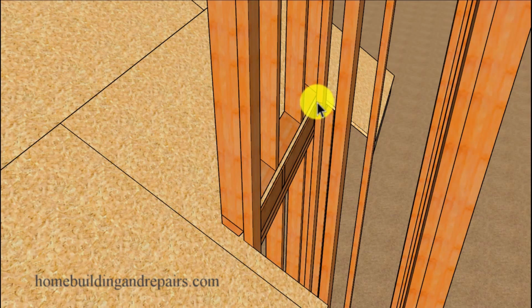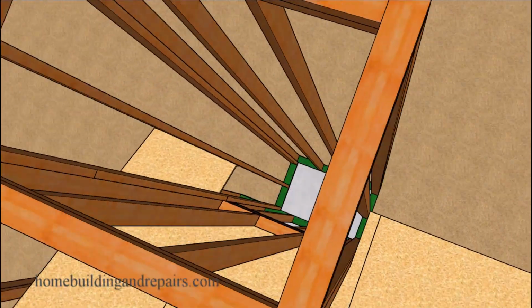Now here's the example of what I was talking about. We're not going to be coming off of this mark here. We're going to need to add 3.5 inches to it. This will be the point we're going to be coming off of. The farthest point of the chimney facing the slope of the roof, or the slope of the roof that we're going to be getting our measurements from.